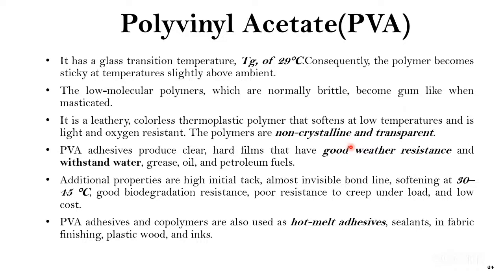Master batch means suppose you are purchasing polymer. You saw that that polymer already has color, blue color, yellow color. In that polymer, they have already added heat stabilizer, antioxidant, flame retardant, as per your application, all additives have been mixed. The color they have added, or if you want to do some copolymerization to it, everything you get. That is known as your master batch.